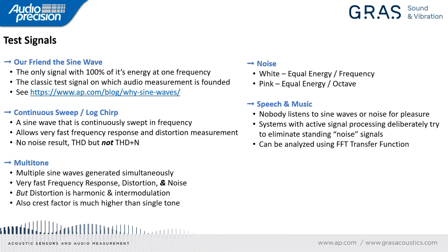So that means that when we drive a sine wave into a device under test, and we look at the output of that device under test, all the energy that's not at the frequency of our stimulus is something else, something usually undesirable: noise, distortion, other products. So in that sense, a sine wave is like a test probe. It's a way for us to probe our device under test and exactly characterize its behavior.